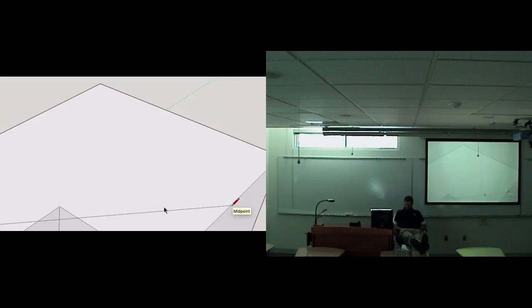inference point. Once you see the tooltip telling you it's the midpoint, follow the original green direction, and SketchUp will infer to the midpoint, telling you exactly how far to draw the first edge. Make sure you see both inferences, and click to finish the first ridge. Then, draw the second ridge to this midpoint. Now that we have both ridges in place, simply draw the line where the roof will fold when we move the ridge lines.